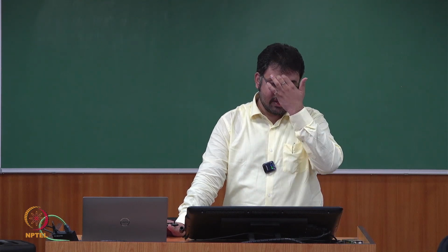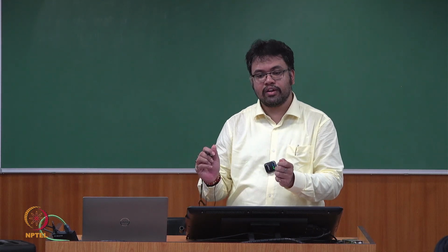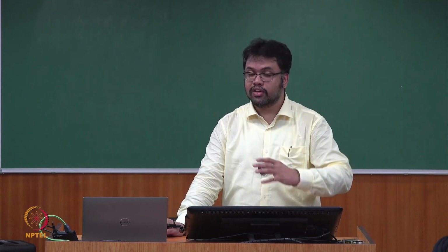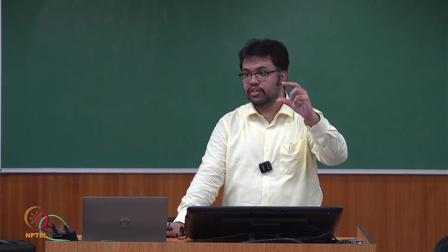So these three factors combined give a stiffness. Once you make a unit deformation, that involves the components of these three things. Here unit deformation means unit amplitude. Don't think of just a deformation; it's a sinusoidal thing, so it's a unit amplitude deformation, the magnitude is unit.